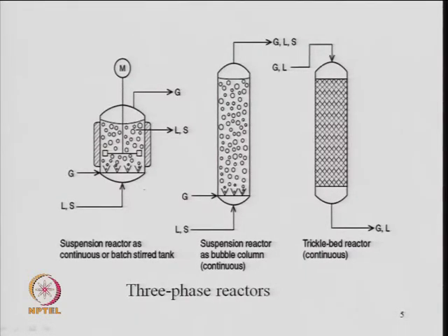How can you make a good contact between gas, liquid and solid, because all these resistances may be important, and how to enhance the kinetics of the reaction. So, all these factors become important when you select the overall rate of the reaction, and accordingly the reactor design is required, or it is important to select a proper type of reactor. This is similar, but this is a continuous type, a plug flow type, that is a combination of CSTR and plug flow.